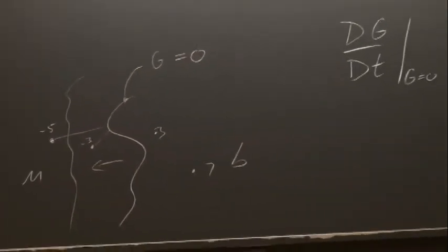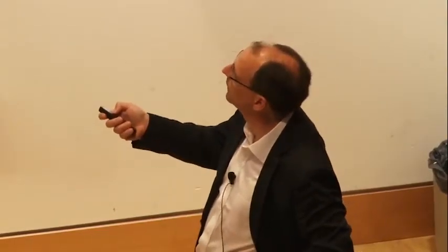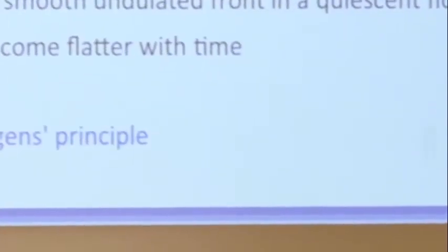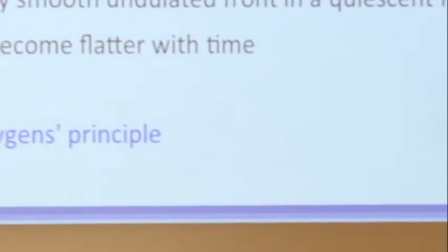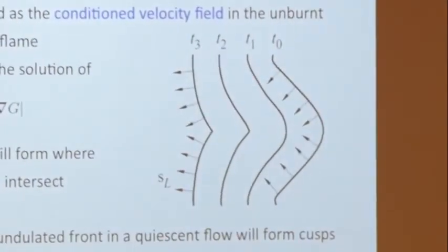And there are different numerical algorithms for this. It doesn't need to be a distance function, it just needs to be regular. So typically, you don't do this reinitialization at each time step. You do it every 50 or 100 time steps, whatever. But so you can use this equation. I'm just saying it's a little complicated to solve.